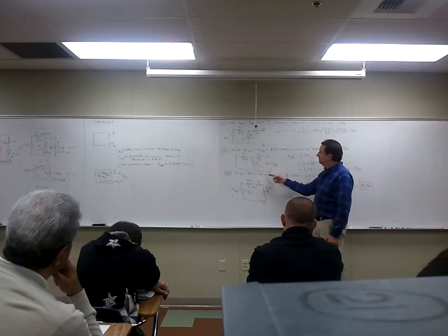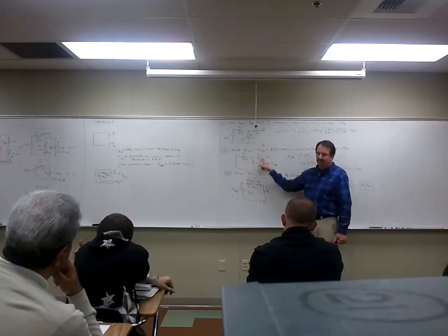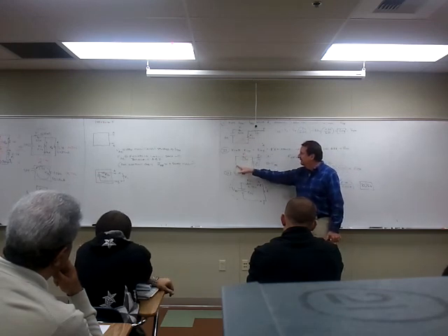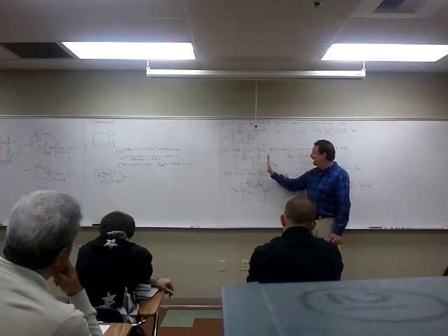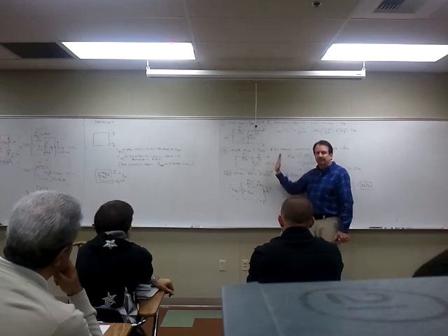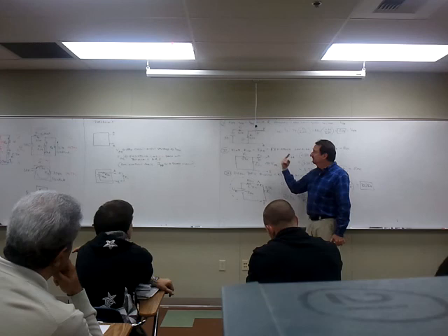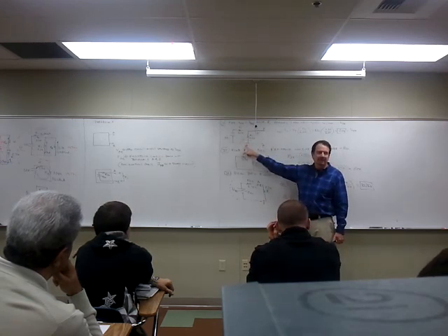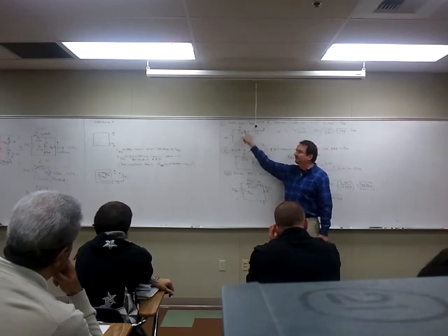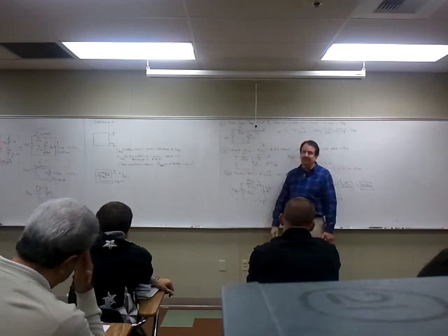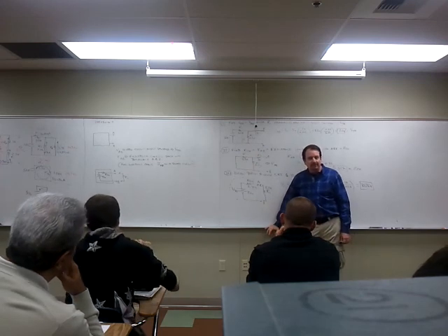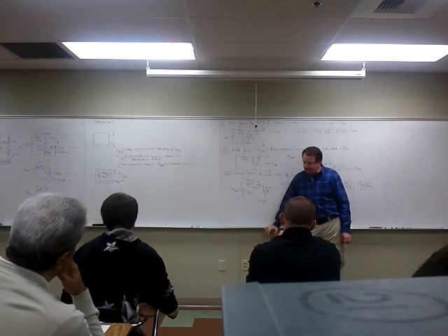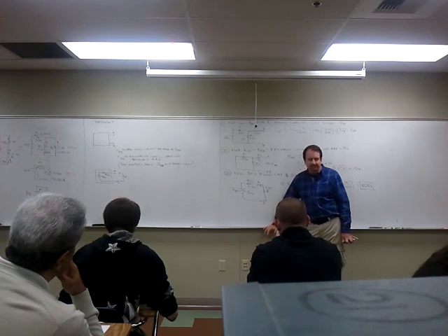It's the resistance looking back in. Now R3 comes into play, and the power source is replaced by its internal resistance. It's as if you put a battery here. What would this battery see as R total? Now let me ask, what's R total in this circuit again? 5.5K. It's simply R2 in series with R1, right? This isn't even in. So this power source sees 5.5K. Is that R total R Thevenin? No, it never is. R total is never R Thevenin.